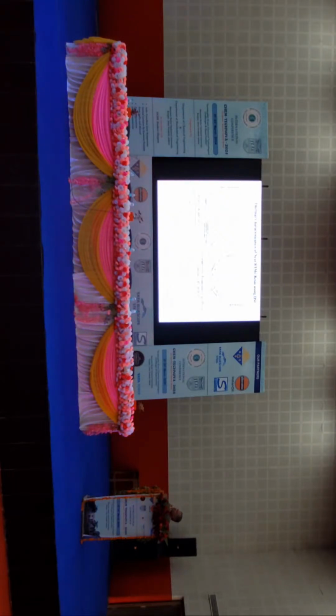Next one, please. In this case, to see the differences between the resins, earlier the curing temperature was 50, 60, 70, but in this case it is a high temperature application resin, so you can see that it is 180 degree, 200 degree and so on. So at the end you can see that, with the cure kinetics data, with just 3 or 4 experiments in the DSC, I can completely obtain the cure profile of the resin, without, because you cannot expect this data from the supplier. Okay, right. So next one please.